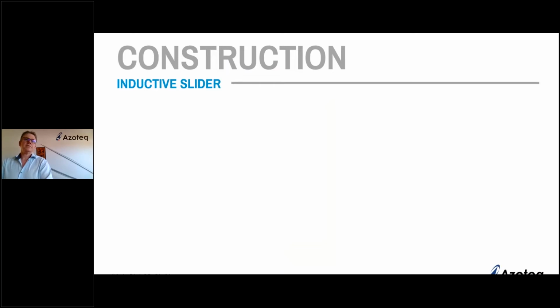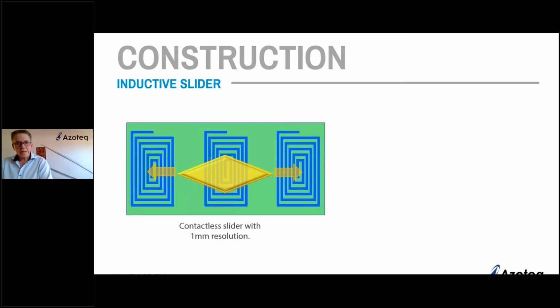The third idea or application for the inductive sensing is to make a slider. Now, if you ever tried to make a waterproof slider interface, that is significantly more cumbersome and challenging than making a button waterproof. Again, with the inductive sensing, it can be a very simple construction.